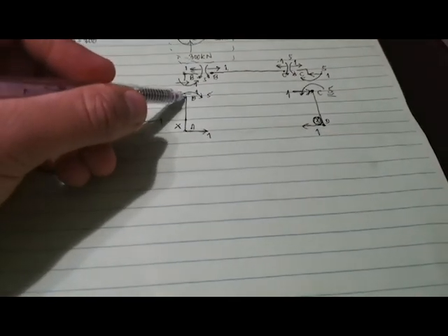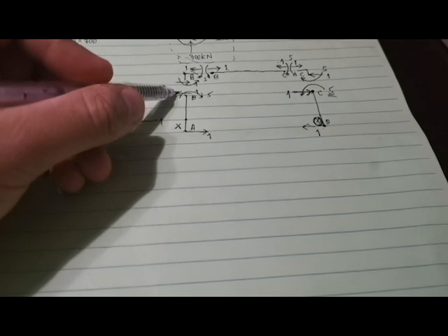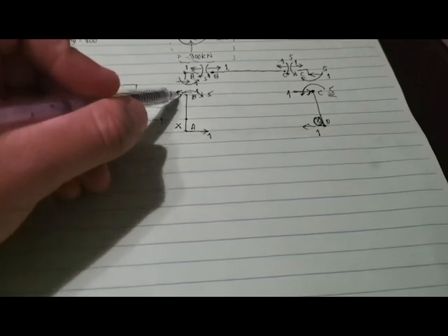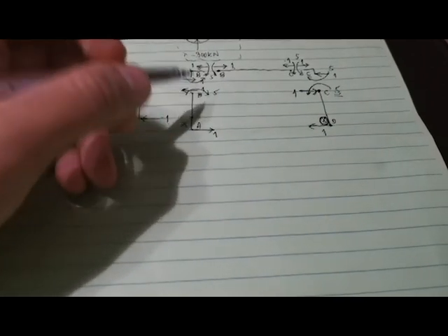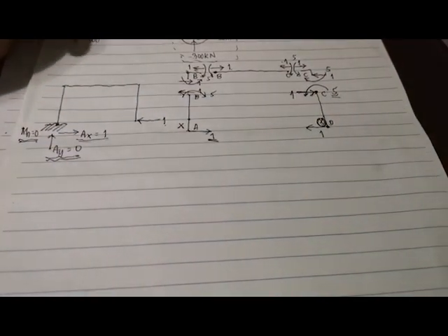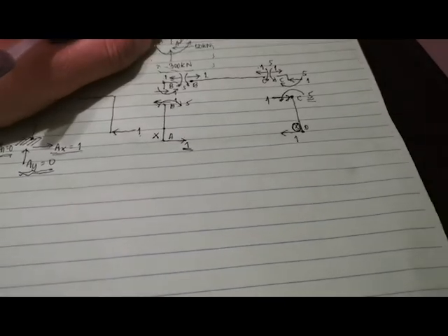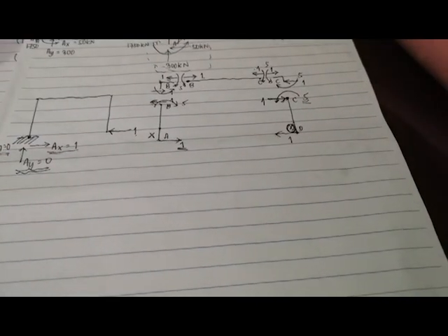Okay. And because of this we have a counterclockwise moment, and we have a load to the left here. Of course, our reaction is understood to be going to the right. You can also check by doing equations of equilibrium.